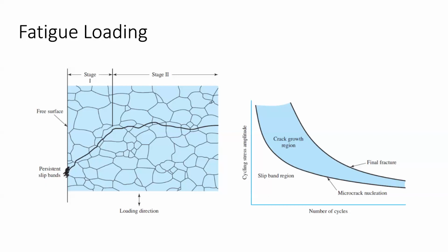You had the combination of a really high stress concentration with a repeated load from the wheel rotating. So even though the part looked like it had a factor of safety of 4 in the FEA, if you're not careful about these things, then that fatigue loading causes failure in, I think, like 1,000 cycles, so 1,000 rotations of the wheel. And for something like a car, that's just not acceptable, right? So it was a really innocuous thing where they chose the right material, but because they didn't design the geometry right and didn't recognize the aspects of fatigue loading, it caused the part to fail really critically. I think they had like 2 days to machine it before they went to competition. So not a really good scenario to be in.